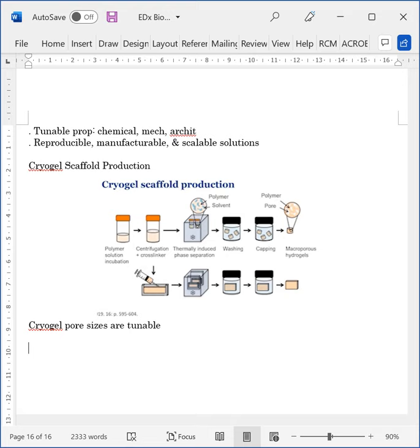The challenge with electron microscopy is that the sample has to be dried. So the pore size we get is not exactly the same as what we see in the fully hydrated sample under confocal microscopy, but this shows us the interconnections, which is very nice. We can then control the pore morphology, so we can regulate the way that freezing process occurs, and that gives us a lot of control about the structure of the pores inside these gels.